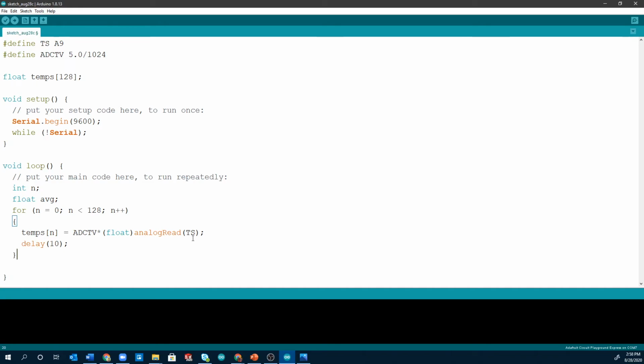If you want to ensure this, an easy way to do it is to divide each of the values by the 128 as you're adding them up. Remember that division is somewhat commutative with addition in this case, since we're summing up the values, dividing the sum by 128 would be the same as dividing all the values by 128 and summing them up.